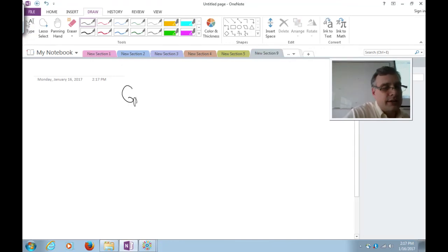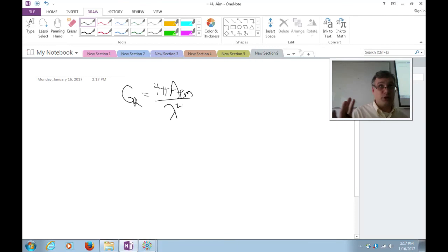Remember we said that at a receiver, my gain is 4 pi times the physical area, the electromagnetic area. If you have more physical area, you're going to get a bigger cookie cutter, right? So generally, the bigger your antenna, the more directional you can make it, the more aperture you can pull energy out of. That means you're going to have to point it, because you're going to get gain whether you want it or not in that particular direction. And if I plug that into my Friis free space equation, I get this.